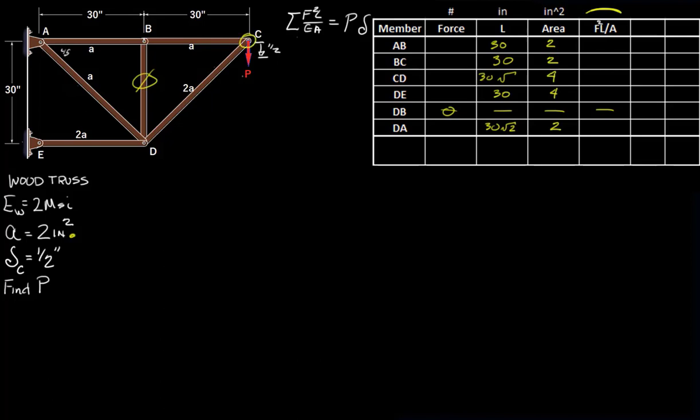And you can recall from statics we can do this by pins. So if I start with pin C, we have a force P acting down on it, and we'll just leave it as an unknown. And we have 2 members coming off of here. And we know that this one has a 1-to-1 ratio on it. It's 45 degrees. So summing the forces in the Y, if we have P down, we have to have P up here. This has no Y component. And in the X direction, that has to have a value of P in that direction because that is in compression. And then summing the forces in the X, we could say that this would have to be P. So that gives us member BC here, which is P.